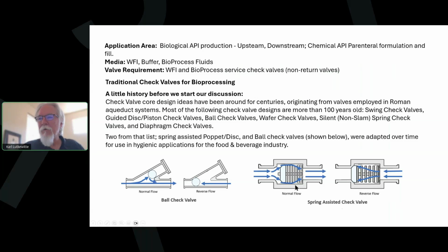and they're pretty simple as well. So in this case, you've got flow entering through the inlet here. It contacts a thermoplastic disc that has a spring behind it that's in compression. And when the force of flow, the pressure at the inlet, exceeds the spring force that's trying to close this disc, of course, the disc will compress the spring and I'll get flow through, around, and through the springs and guided spring through the outlet.